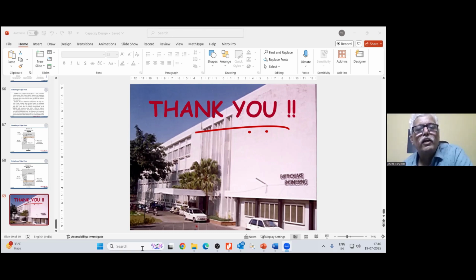And it's a perennial question. Using a floating column in a tall building is safe or not? The question perhaps is, can we use a floating column or not? Yes, you can use a floating column. You can design for a floating column. Make sure that it is not a strong column, weak beam. Here it is a strong beam, weak transfer girder and weaker column. So the transfer girder on which your floating column is there, the transfer girder should be stronger. Their hinge should not form.